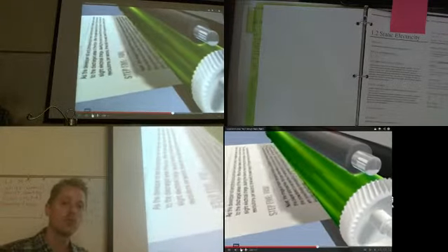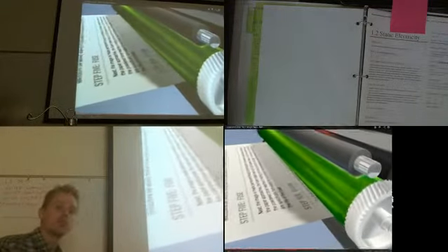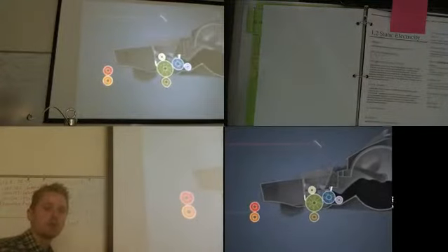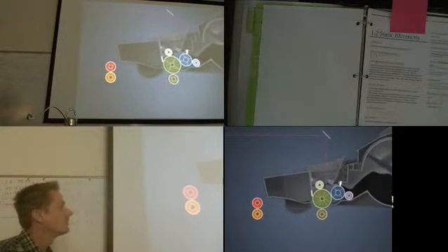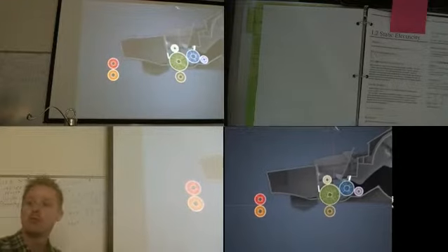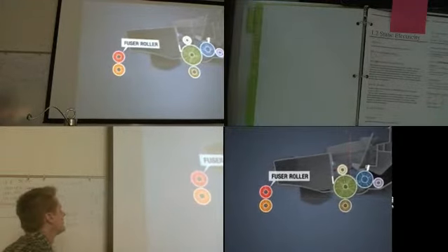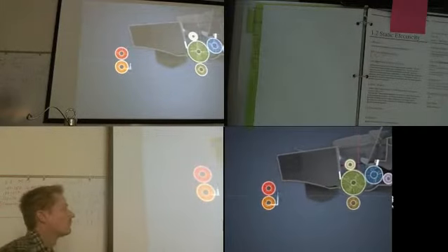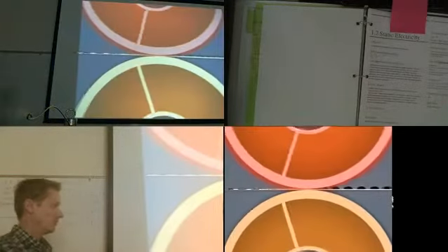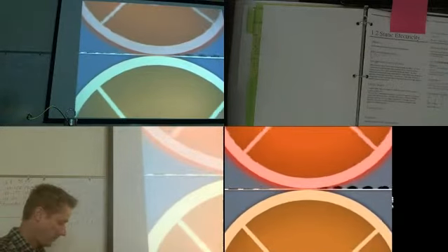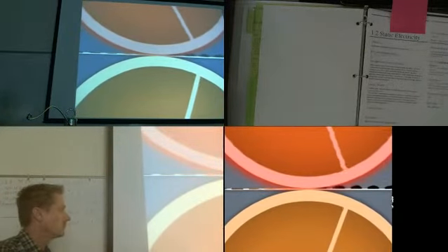Of the paper, ensuring a complete image transfer. Next, the image is made permanent through a combination of precisely controlled heat and pressure. As the paper approaches, the fuser rollers heat up to 225 degrees Celsius. In just 23 thousandths of a second, the powdered toner reaches its melting point and bonds onto the page.